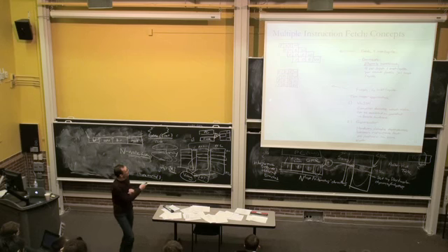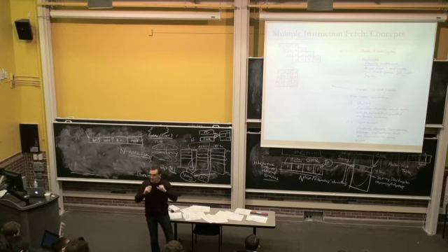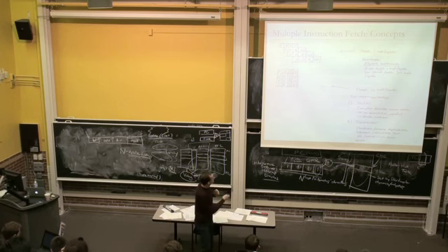Okay, so the upside of superscalar is your throughput increases, right? You can finish multiple instructions per cycle. I'll define retire very soon. You can finish execution of multiple instructions per cycle. The downside is that now you need to detect the dependencies, and you need to ensure that these instructions can execute concurrently. Your hardware becomes more complex. The other way of doing it, VLIW, now the compiler needs to figure out which instructions can be executed concurrently and pack them together. This way hardware doesn't need to figure out the dependencies. Again, simple hardware, complex compiler.